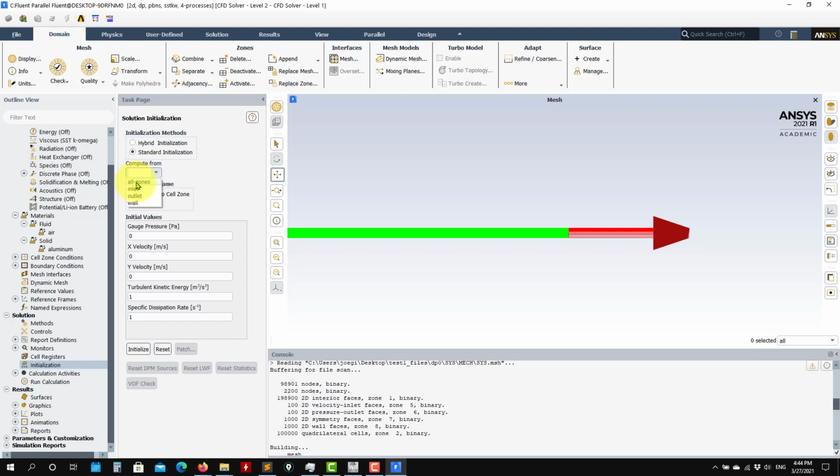So if I go here, compute from the inlet, see here that it is computing these values. And as you recall from the lecture about turbulence estimates, as you go there, you will see how you can compute the turbulence estimate, and you will see that we get similar values. Again, as you go to the help, you have the help here, you will see all the equations and correlations implemented in Fluent.